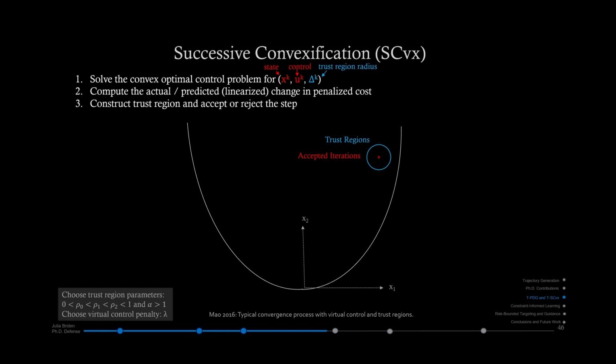And to solve the Six-DOF problem, it's different from lossless convexification because now we have non-convex state constraints that can no longer be losslessly convexified. So then typically a successive convexification algorithm is used. So instead of just solving one problem, we're now solving a successive set of convex optimal control problems. And while each one of these problems has a global minimum, you might still converge to a local optimum, and that's the reality of non-convex optimization.